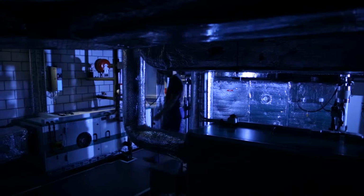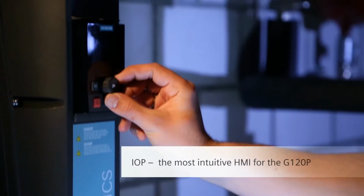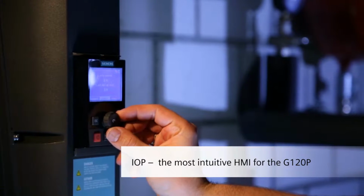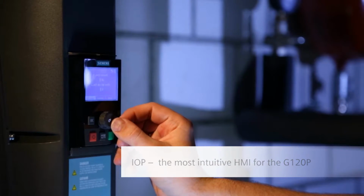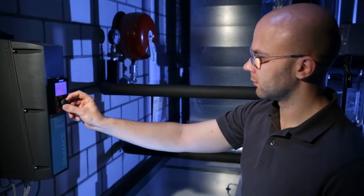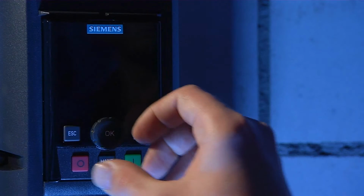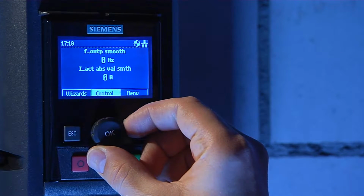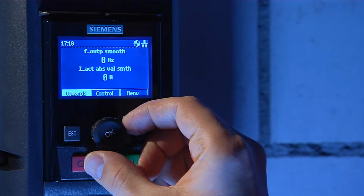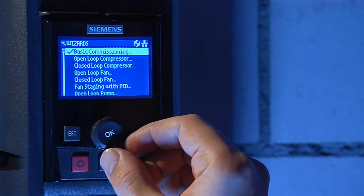Setting up the G120P variable speed drive using the Intelligent Operator Panel, IOP, is very simple. See for yourself how easy and quick it is to set up the G120P for control via Fieldbus, in this case, Modbus RTU. Use the selection wheel to navigate to wizards and confirm by pressing OK. The IOP offers many wizards optimized to suit your application and setup needs.